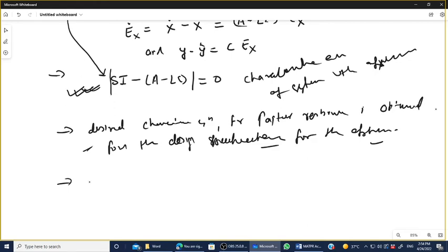Generally, as you know, the response becomes faster as the pole shifts towards the left hand side. So we have considered that the pole location of this observer is 10 times greater than the specification pole location. That is, how much more than the specification pole location, 10 times higher than this, okay.